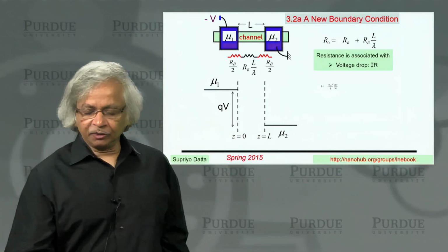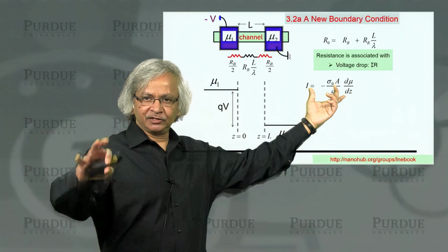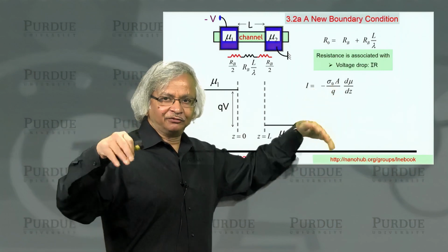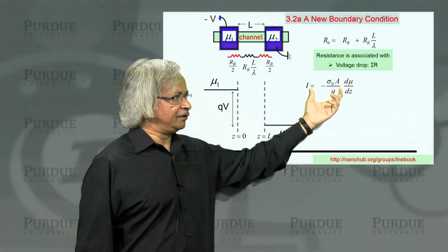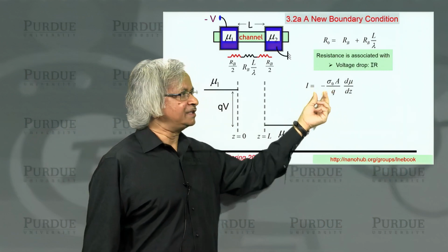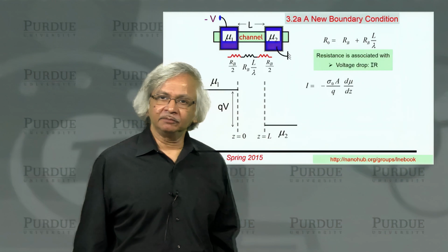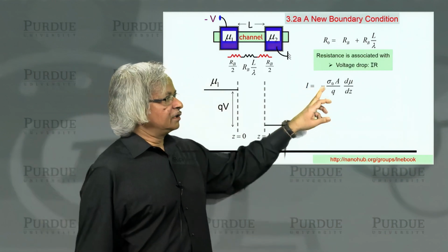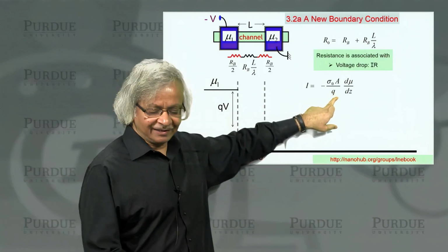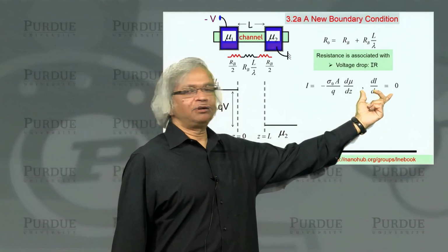Now, what you could do is start from this diffusion equation. Again, we discussed this in the introductory lecture, that it's actually the drift diffusion equation, really. It includes both drift and diffusion. But this is the basic equation which says that current is proportional to the slope of the electrochemical potential. Now, there's one more equation you need in order to be able to solve this, and that's what's called the continuity equation. So what's this continuity equation?